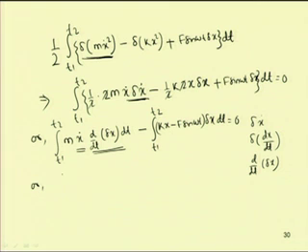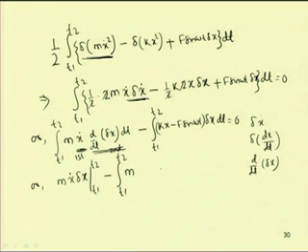The first function remains as it is and we integrate the second, which becomes del x, evaluated from T1 to T2, minus the integral from T1 to T2 of the derivative of the first, m x double dot del x dt.